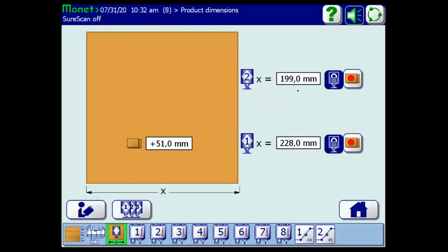You'd be missing detected glue because the glue sensor wouldn't see the glue that fell on the floor in between the cartons. So you'd create failures for your rejection. And then the question is, would our reference point of the actual lead edge be kind of missed or offset at that point? That could be a potential issue if you're using the trigger lock feature.